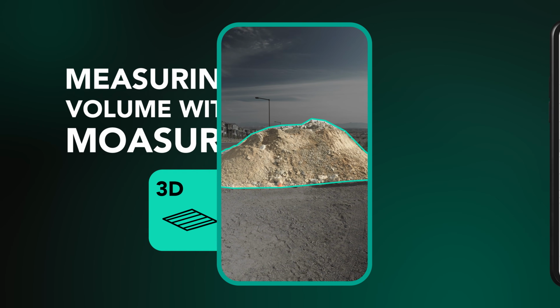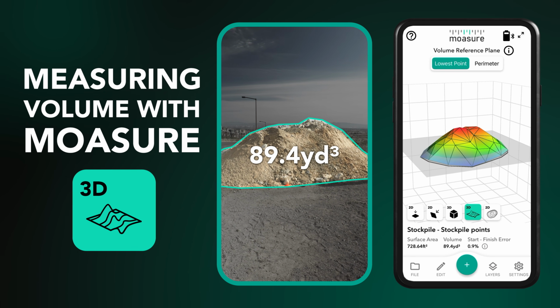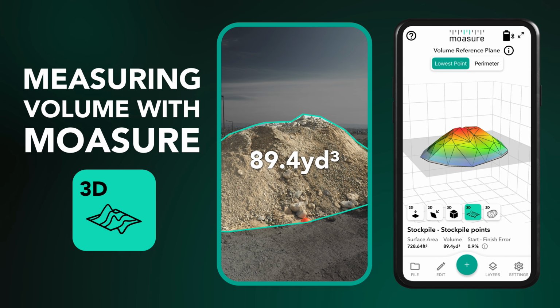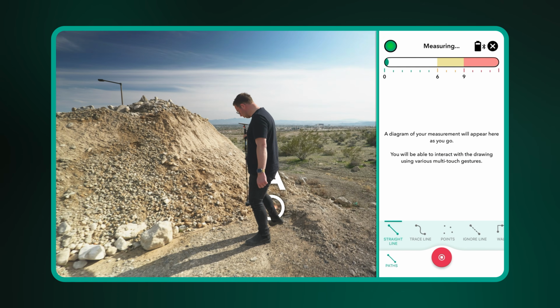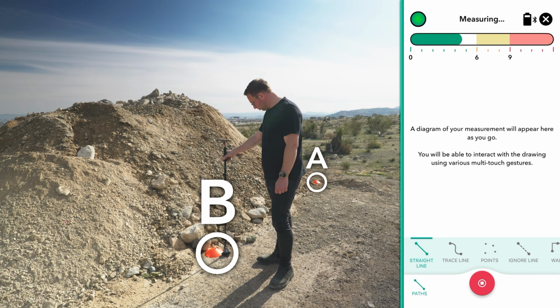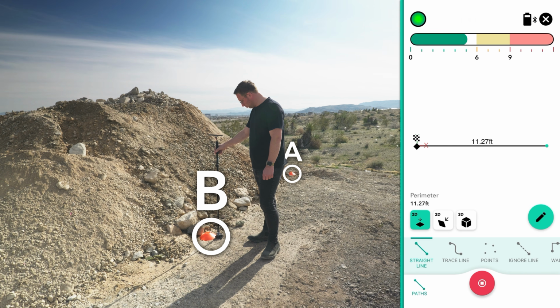In this video, we're capturing the topography and volume of a stockpile to calculate how much material needs to be removed from site. We begin by measuring the perimeter of the stockpile. Before starting, points A and B are set out on site using orange cones. These mark our starting points and will come in handy later when aligning the volume layer.